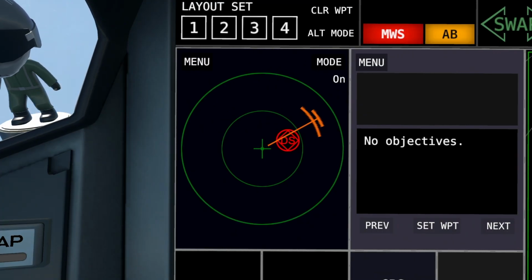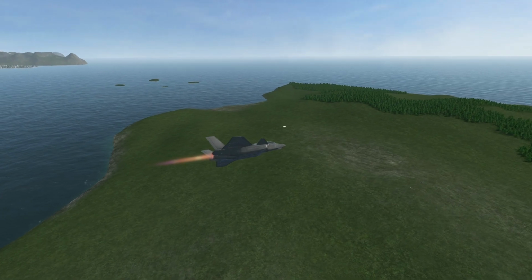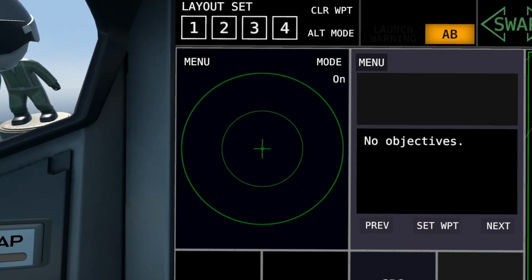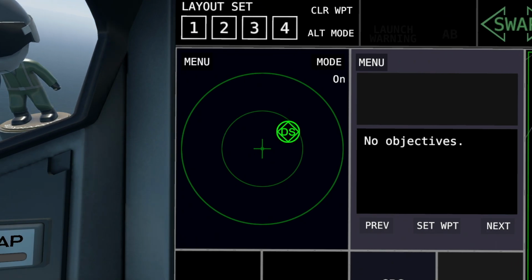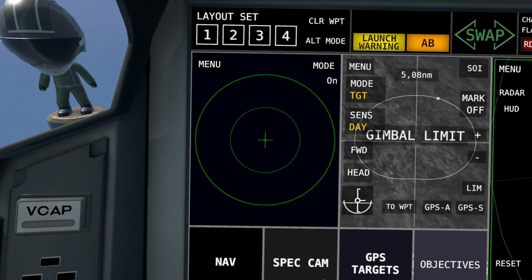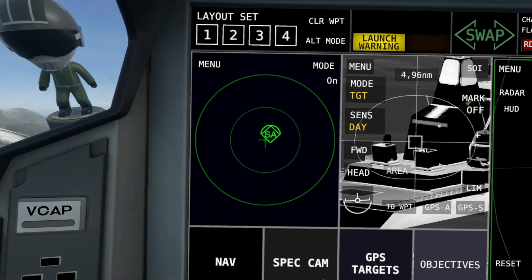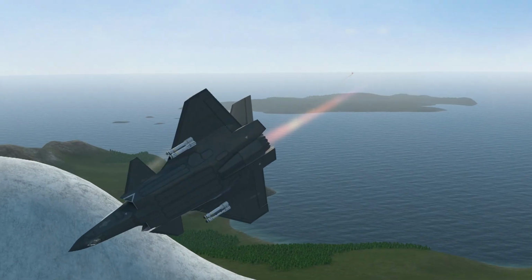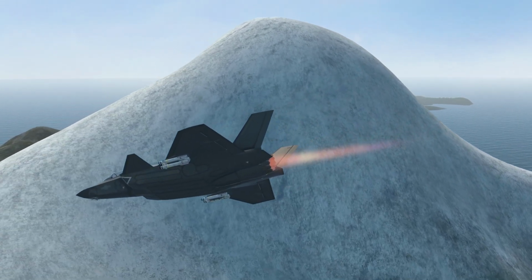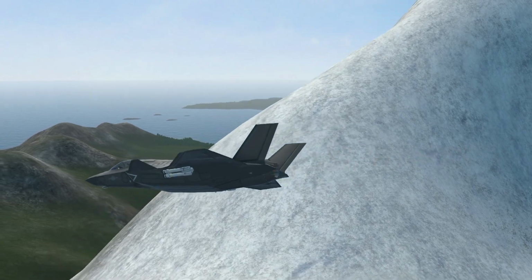Using all this information, we can make the correct evasive move according to the missile type and situation. In the case of a radar missile, we will get a radar detection and lock warning from the RWR before a missile launch warning. If you immediately get a missile launch warning without a lock, then it's most likely an infrared missile. For radar missiles, if possible, and the missile is not in pitbull, we try to break the line of sight from the radar by taking cover behind a mountain.